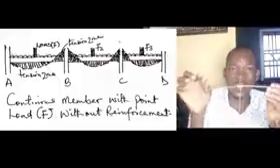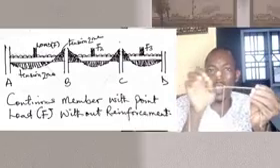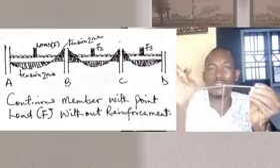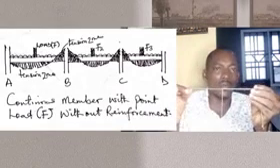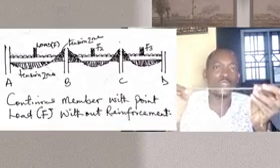Now you can have it in this direction up to about 1, 2, 3, 4 and so on. You can have so many columns, with the beam on the columns. When you have this kind of support condition, just as you are seeing in that image, where you have about column 1, 2, 3 and 4, you call it a continuous beam. This is a support condition which is a continuous beam.